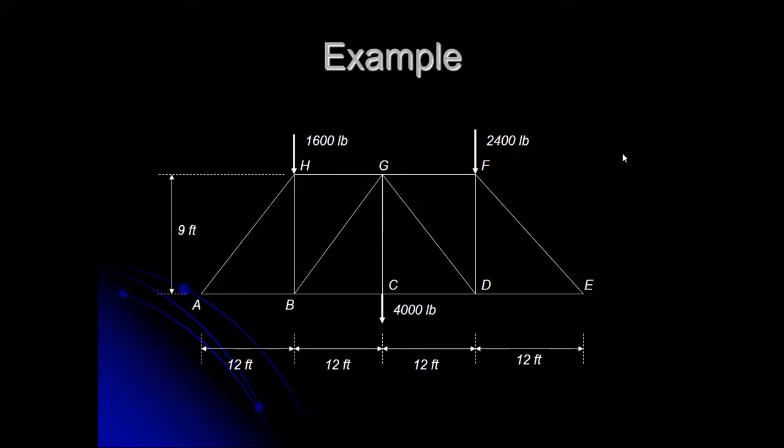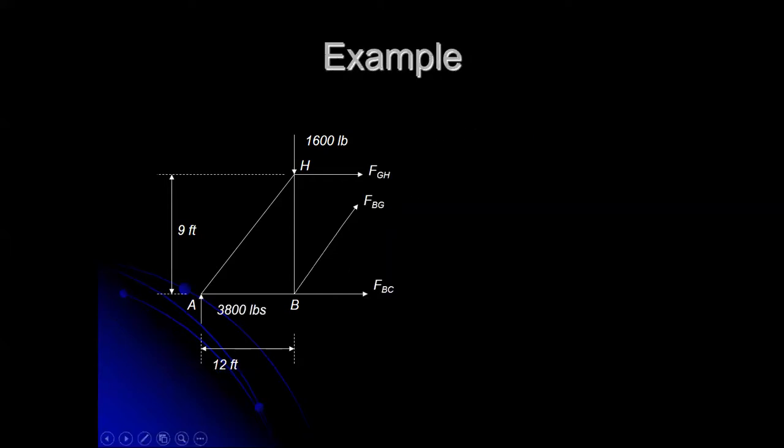If I eliminate everything outside the system boundary, that whole right side of the truss is going to disappear. And all that will be left behind are forces, the forces exerted on the members that we cut through by the rest of the truss. If I flip back and forth here, there's the whole truss, there's my cut truss.